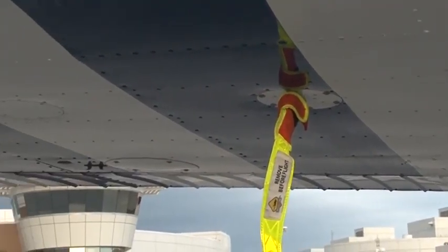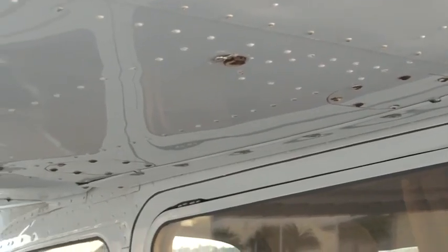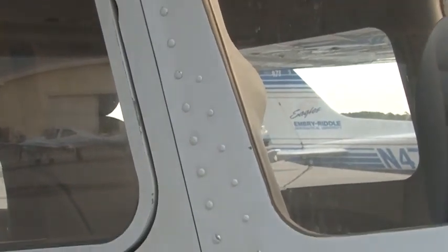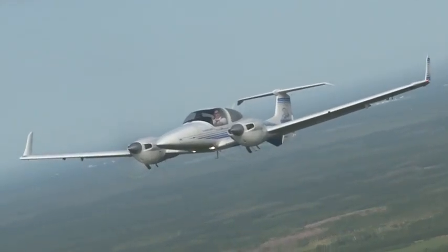Skin friction drag is caused by the rough imperfections of an airplane's surface. A good example of this are the rivets located on the airplane's skin. These bumps disrupt the airflow from otherwise flowing smoothly along the surface. Keeping the surfaces clean and waxed, while also utilizing flush-mounted rivets, will minimize the production of skin friction.